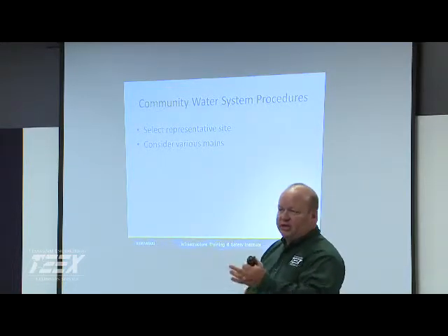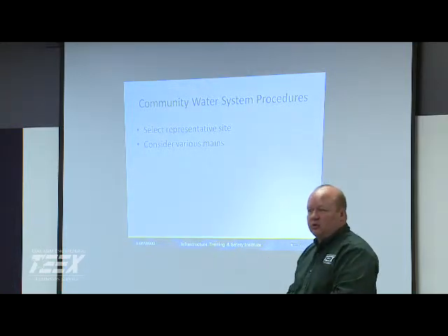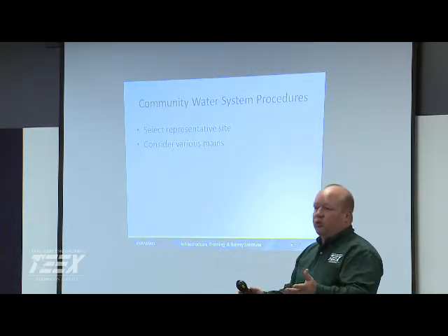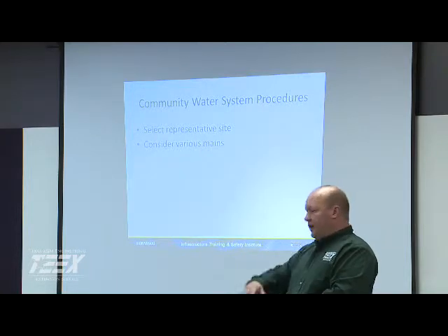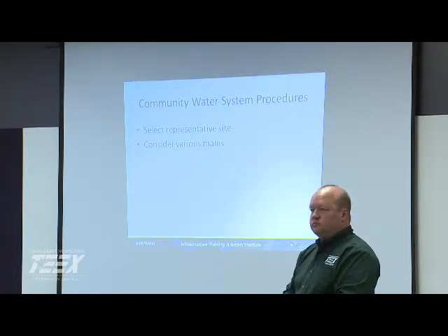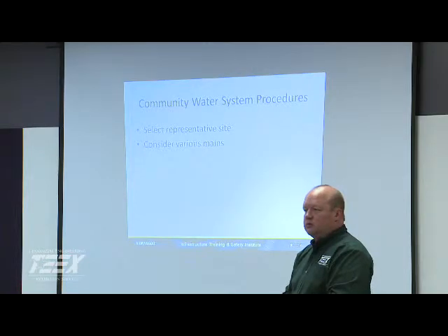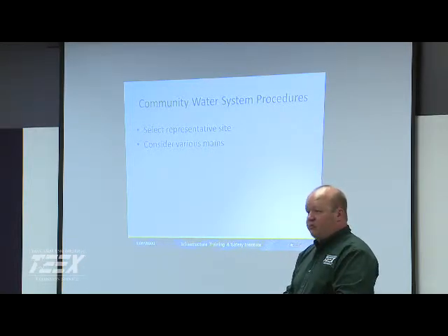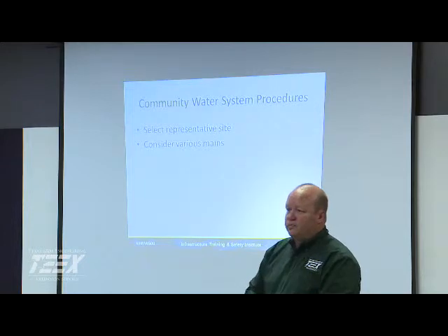Yeah. So on the gas ones, are they underground? The gas valve? Yeah. They're just quarter turn valves, but every year you gotta document it, and you gotta turn them an eighth of a turn. I mean, you don't shut them completely off, but they gotta be able to turn, and then you gotta record them and document it every year. Yeah, and that's a lot of man hours in itself, right? Oh, yeah. It takes 2 guys probably 3 months to do the whole system.